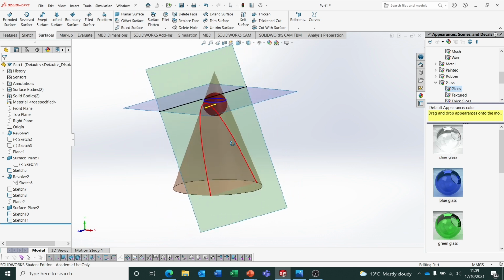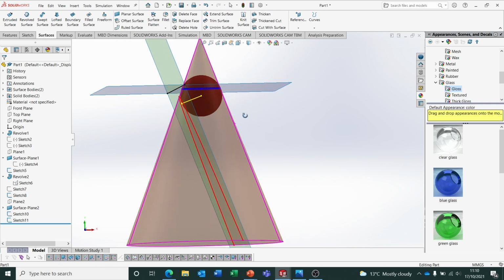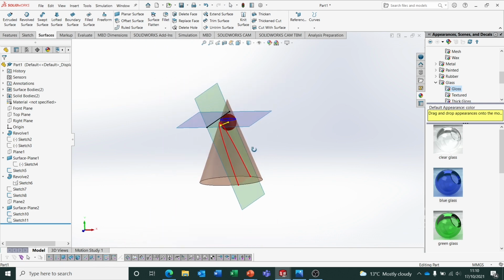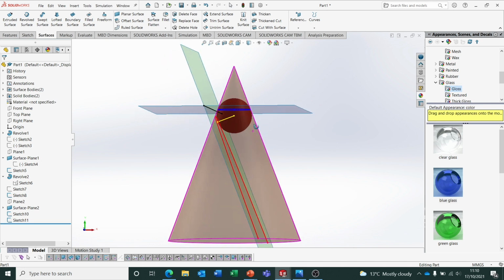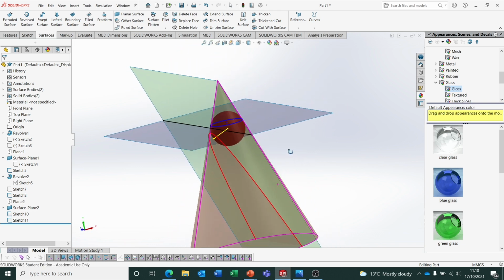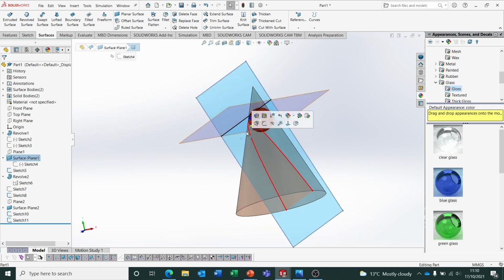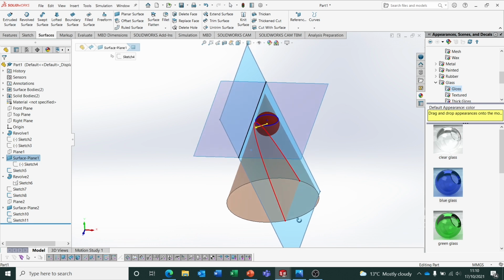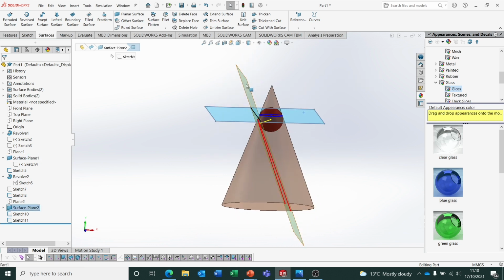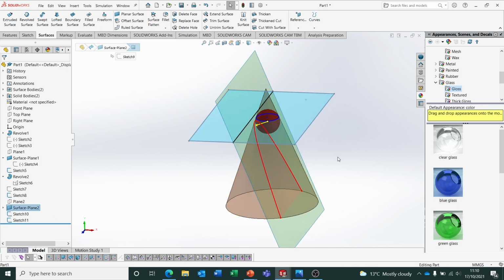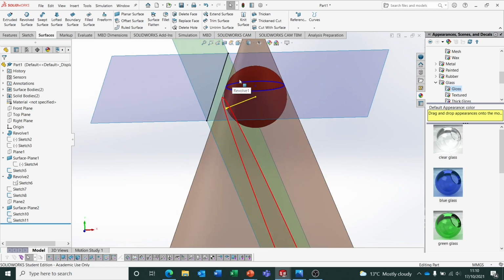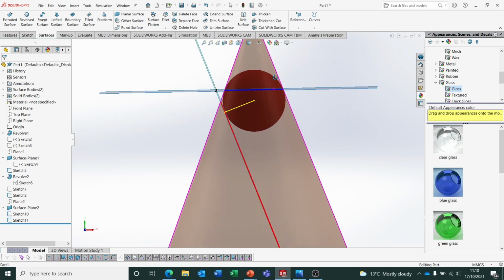Okay, and there is the model now of the parabola. Inside the cones, we can see the cut surface, how it was made, and it was made by creating a cutting plane parallel to an edge of the cone. The focal sphere then is a sphere that fits inside the cone, tangent to the edges, tangent to that plane there as well. And the point of contact between that sphere and this surface plane gives us the focus of the parabola. The intersection then between this plane and that plane gives us the directrix. Okay, and that top plane there, or the horizontal plane, is found by creating a line of contact between the cone and the sphere. And that's the height it rests at then.